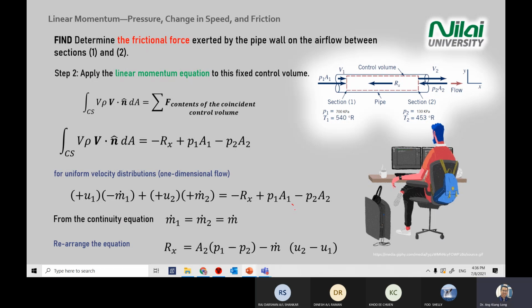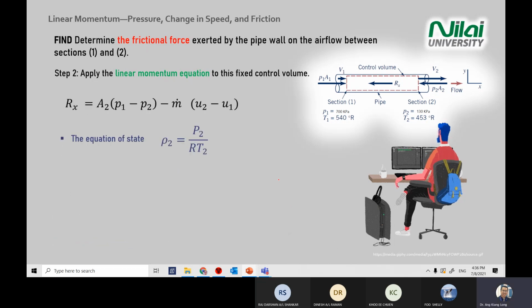So far we're still at a mathematical model. It doesn't link with the control volume analysis yet. Yeah, a bit, but not much. The next is just substitution. What is important here is that you want to find the m dot equal to rho AV. In this case, you're not able to find the rho directly because the rho is not given and it is air.